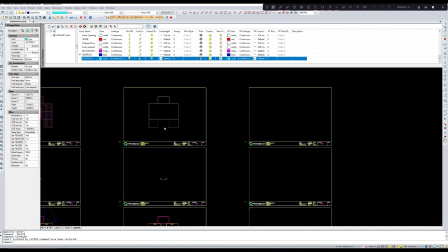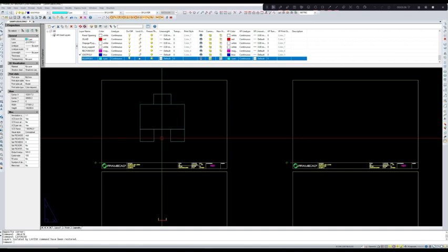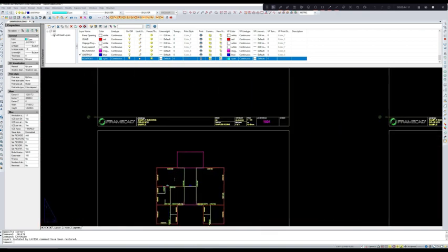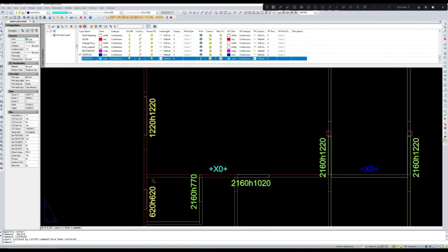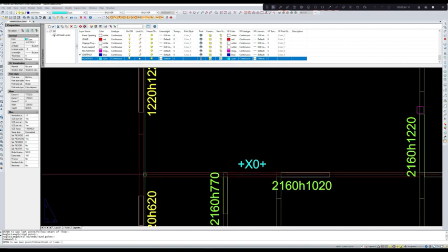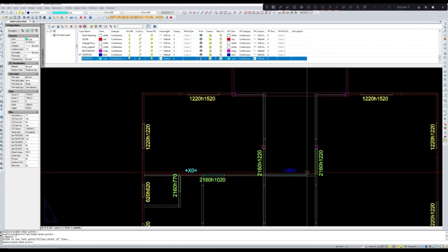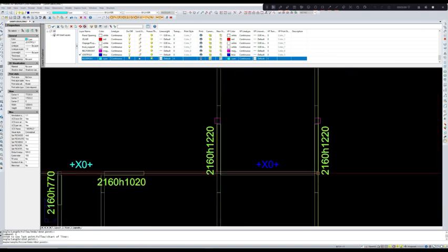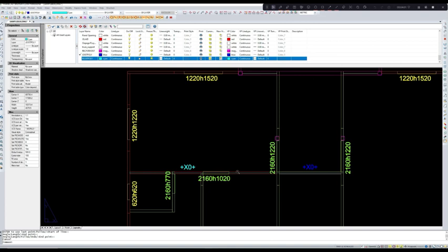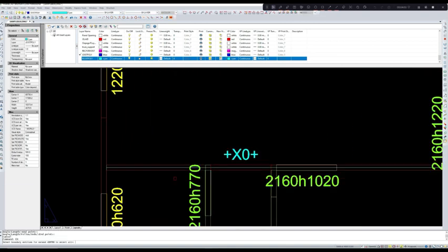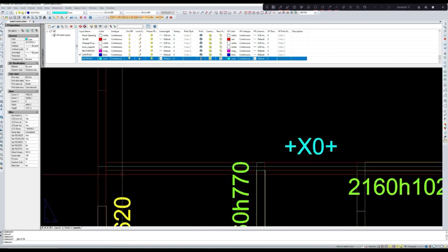So we have this truss, our load bearing wall outline. Now we have missed one of the walls, which is again load bearing for these trusses. So let us make a center line from this and draw a perpendicular up to this point. Extend it to here. Delete this point.